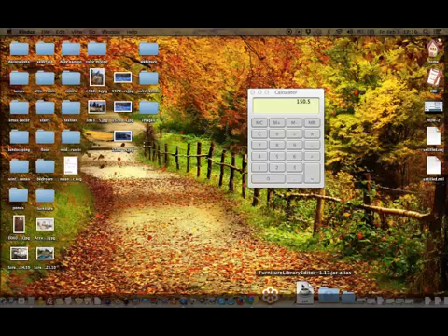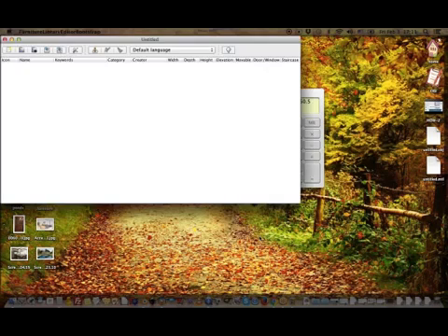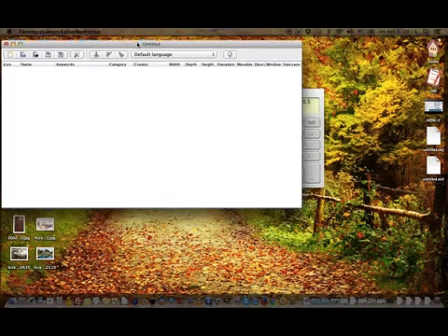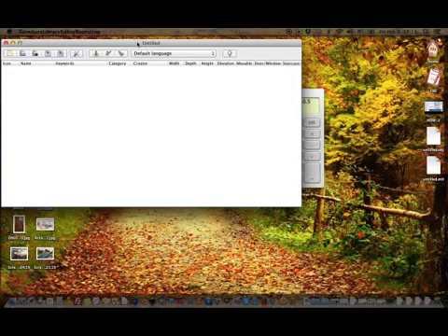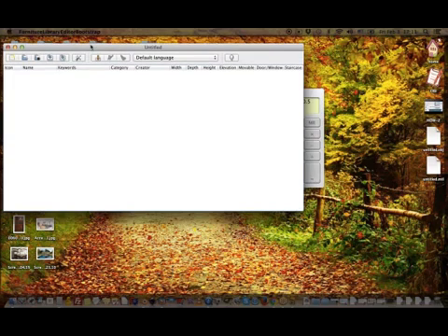Okay, so there's another piece of software on the Sweet Home 3D website, and it's called the Furniture Library Editor. I'm just going to open it up. Remember, I designed that module, and then I created an OBJ out of it, right? Now, I can actually take a bunch of modules that I created that way and create a library with it. I use this piece of software called the Furniture Library Editor Bootstrap, which is basically just a Java applet. So I want a new library. So I created a new library.